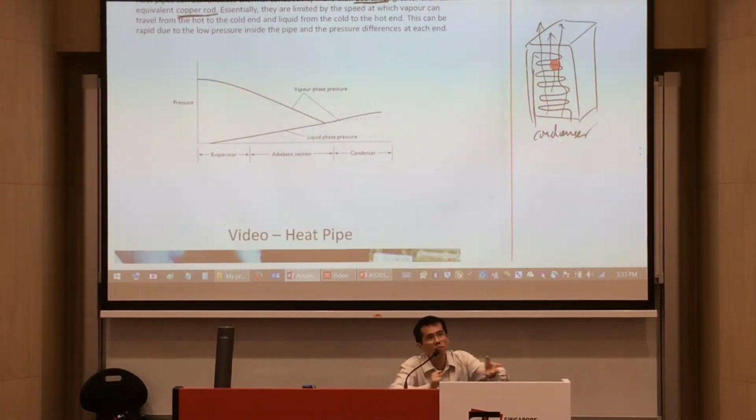That's because the pumping compresses all the molecules closer toward each other, very agitated, hence the temperature increased. So in the refrigerator, there's a compressor to compress this working fluid. After compressing, it's passed to the back to let it cool down by natural convection. Why it needs to do that is part of the refrigeration cycle. I'm not going to talk more about the refrigeration cycle, but there is that part that needs to be cooled down.